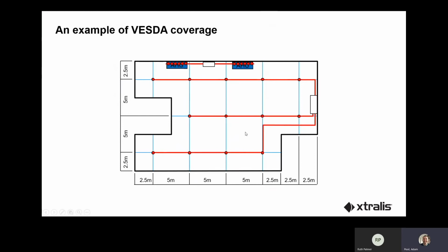So here's an example, a very, very basic computer room. It could be this simple. It may not be a very advanced design system, so it may not have containment aisles. But in this case, we've got an aspirating system covering the room space, and each of the sampling holes, taking the place of an optical smoke detector, is covering 25 square meters.